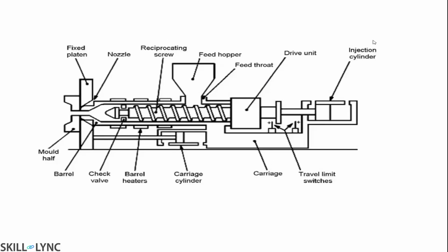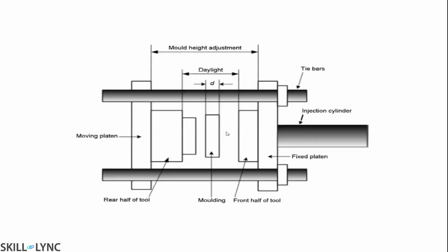We will feed the plastic material in here. There the melting will happen. Then the plastic material pellets will be converted into the melt. From here it will go through this into the mold. Here there will be a cavity, the fixed half. Through this bush, the plastic will enter here and fill the cavity.